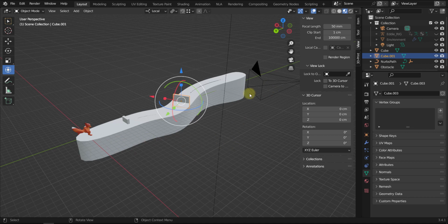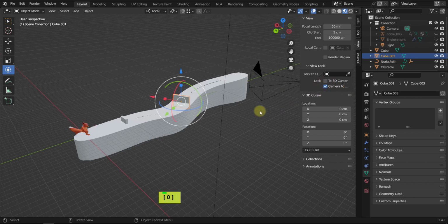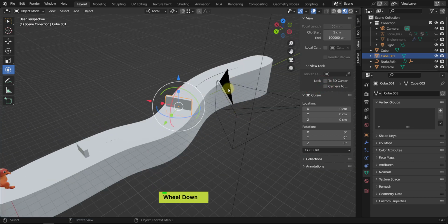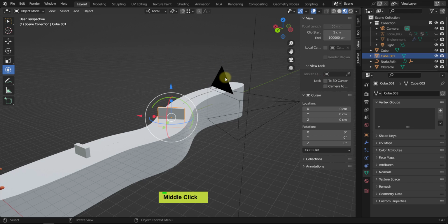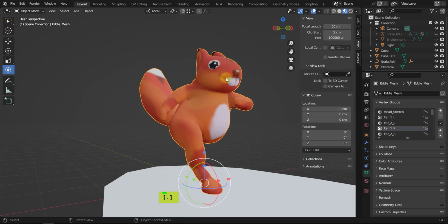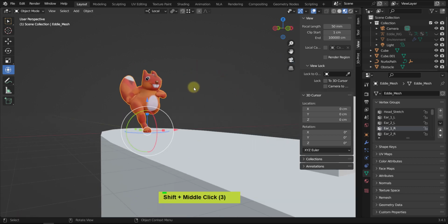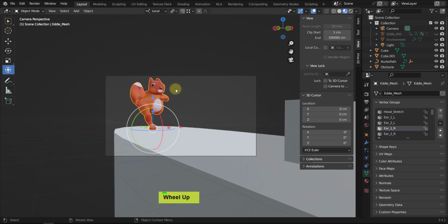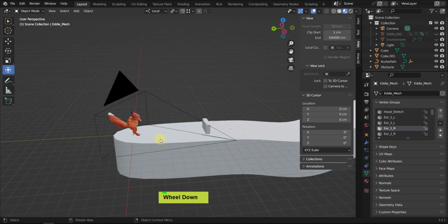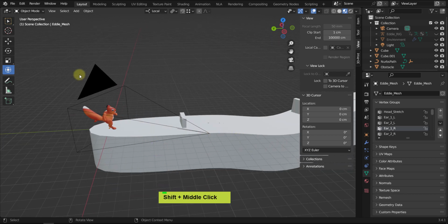Okay, so the easiest way to do it, you can adjust the camera, but here's the thing that you can do. So yes, you can turn on this camera viewport, set again, and move and navigate that way. But let me show you something else. So this camera is active. As you see, this triangle is filled. So you can actually select the figure, zoom in, set your scene, and if you press Ctrl Alt and numpad 0, it will reorient the camera to the desired position. Okay, so that's one simple, fast way, but you have to have a camera selected, active, and then Ctrl Alt and numpad 0. Okay, so this will be our first camera.